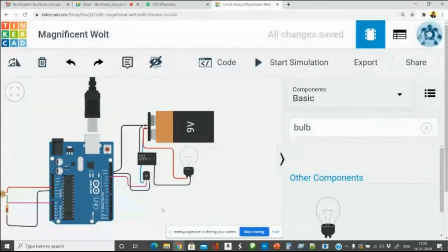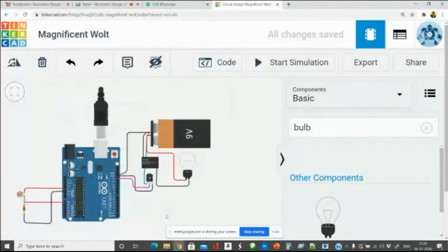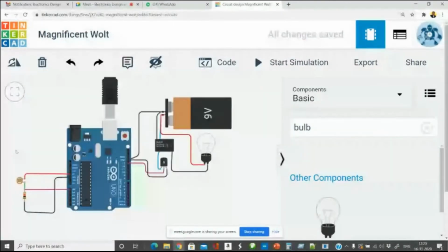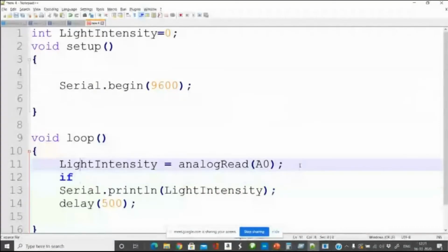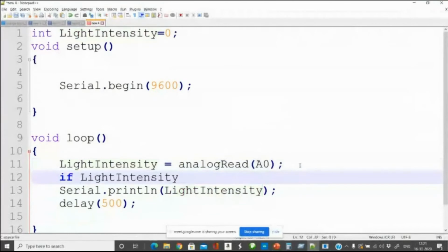So that concludes my control part. So this is my control part. This is my sensor part. You need to decide when should you have the control. Okay, so you have to put an if condition here. Since light intensity is directly proportional to the quantum of light, if the light intensity is above, let's say 300 points, this you can do some experimentation and figure out what should be the value. If the light intensity is above 300 points, this anyway you print it.